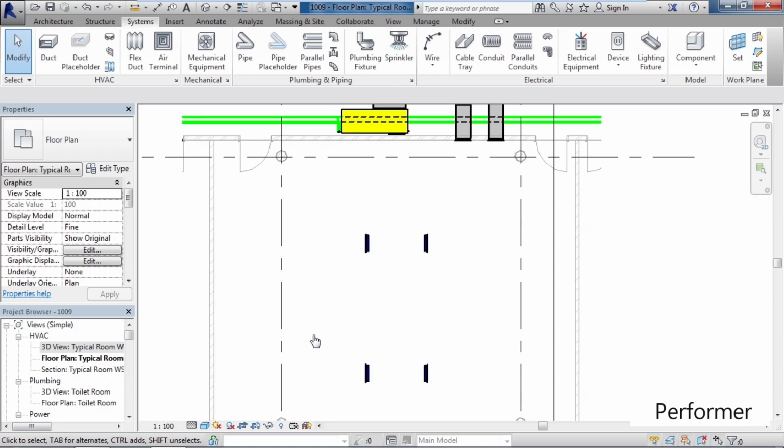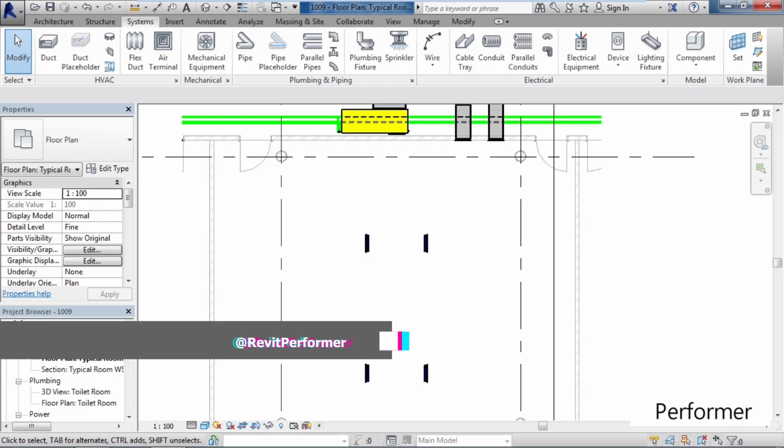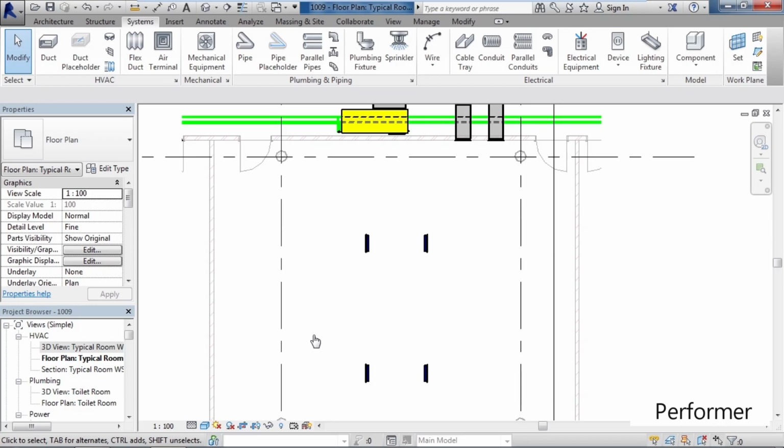In this lesson, we'll cover a method to automatically create duct layouts. Now, in previous lessons, we looked at manual methods of creating ductwork from a supply component to an end result, such as a diffuser, basically clicking point to point. In this method, we'll actually select all of the elements within the duct system and then tell Revit the best route or ductwork between those elements or components.